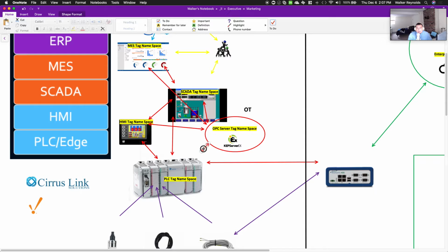Well, because very rarely, for whatever reason, do you find two different manufacturers whose hardware speaks the same language. If it's not Modbus, that is, if I'm not using a series of PLCs that all speak Modbus, then I have to have some type of unifying communication structure. Kepware does that, right? What is Kepware known for?